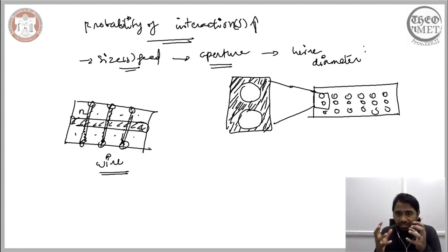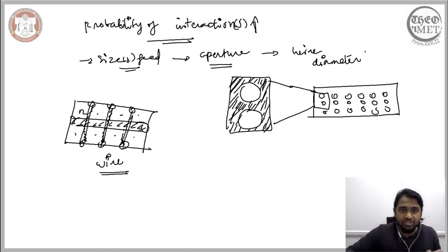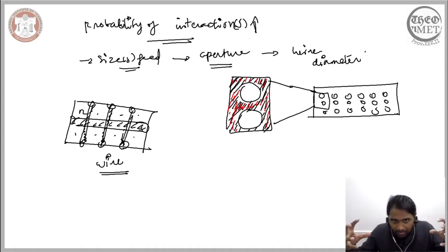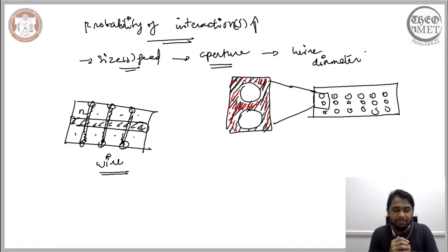When we are considering the probability of interaction, the interaction involves both the interaction between the particles and the interaction between the surface and the particles, and the surface comprises the perforations and also the sections that separate the perforations. In the schematic we just showed the difference between the perforations and the section that separates them. But if you consider the actual build of the screening table, the sections that separate the perforations are nothing but the wires that help build the perforations.